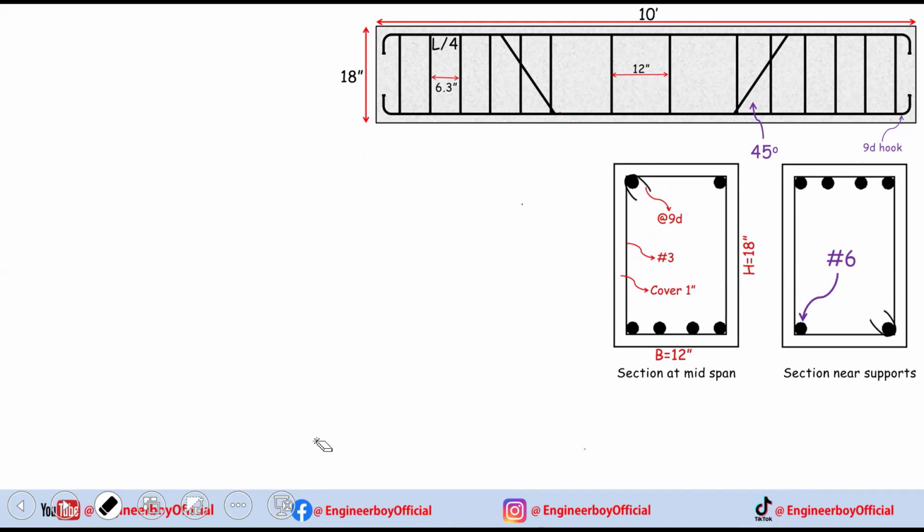If you remember from the first lecture, we talked about how drawing is really important in order to have a detailed estimate. So you must be familiar with drawings. I'm not going to teach the details of the drawing, so we will directly calculate the quantities. So what should be the steel quantity in the given beam? Remember, in order to calculate the weight of steel, we just need the length of the steel bars. And the length can be determined from the number of the bars.